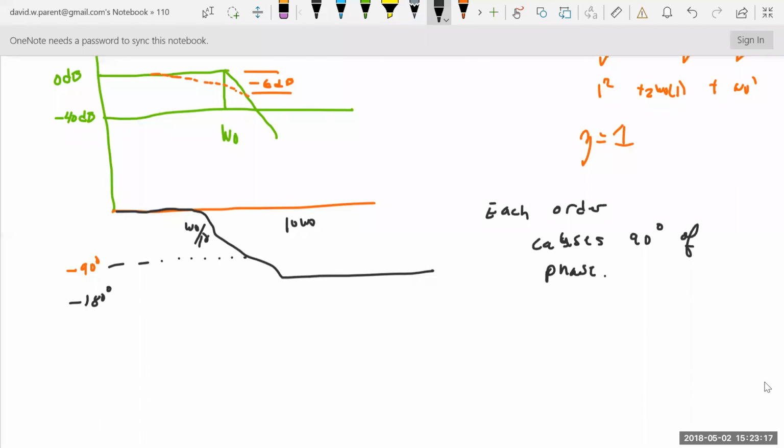All right. So as rough as this is, it shows me everything I need to know. Omega naught, and I can tell that's a decade, and then it went down 40 dB, or I can just make it easy on myself and say minus 40 dB per decade. That pretty much tells me everything I need to know about that Bode plot. It's a low pass filter.